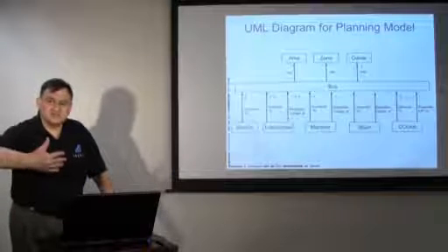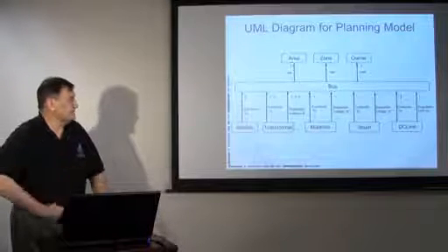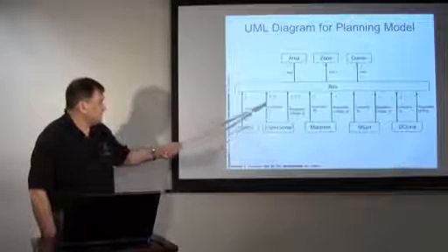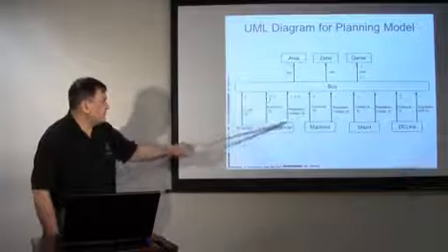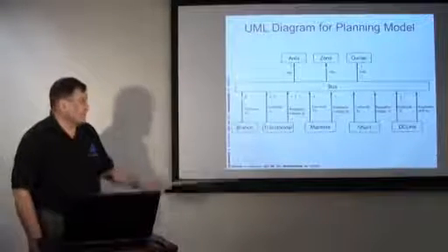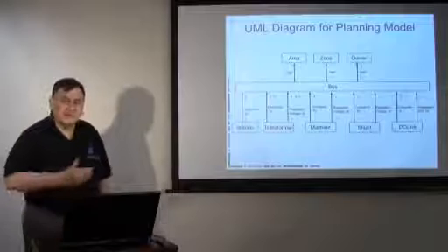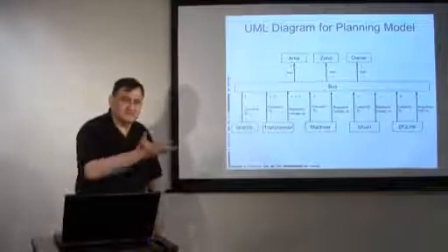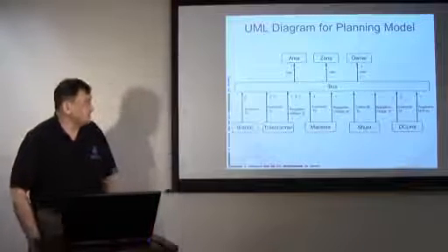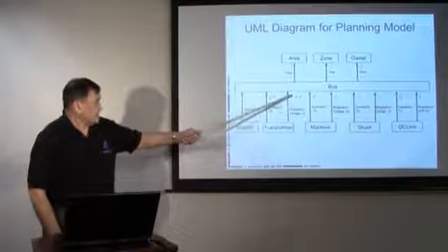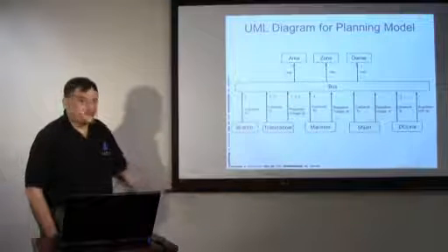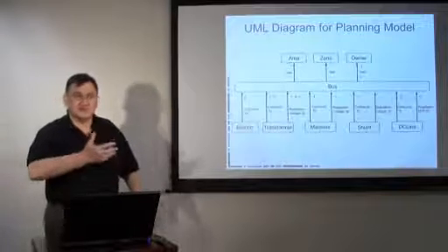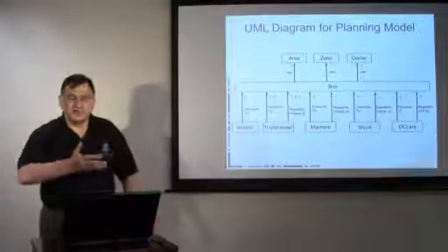There's another aspect, is we can show what's called, in computer terms, the cardinality. And that is how many buses can a transformer regulate? How many buses can a transformer connect to? In this case, we see that it connects to either 2 or 3 buses. And that makes sense because we can have either a 2-winding or a 3-winding transformer. In this case, each of the windings of a 3-winding transformer could regulate 1, 2, or 3 buses. You literally could have taps that could model the primary, the secondary, and the tertiary bus.